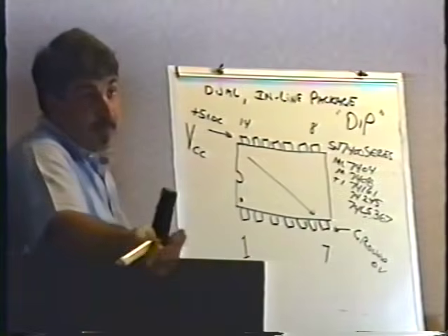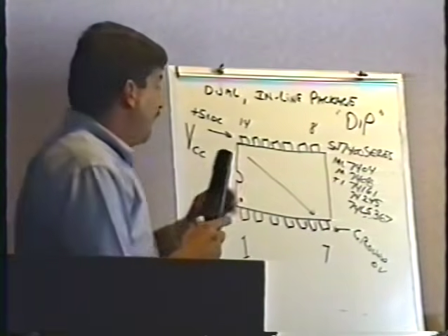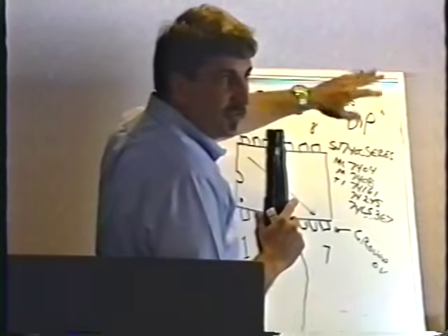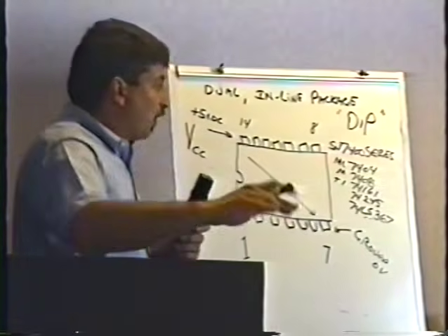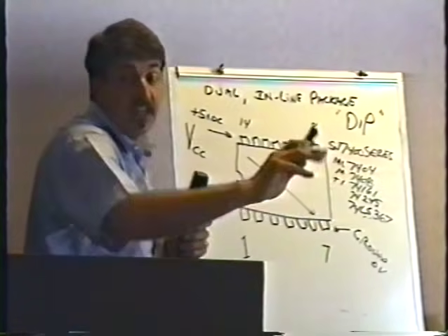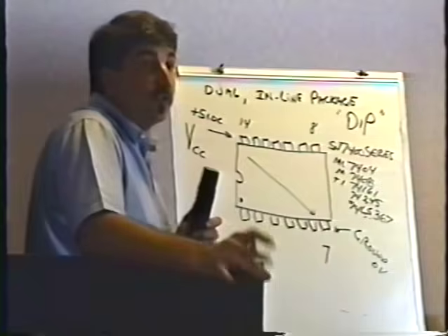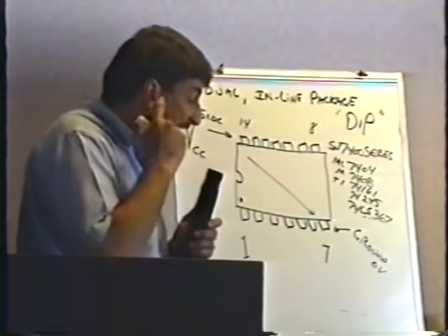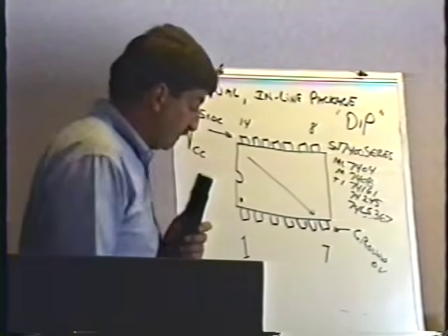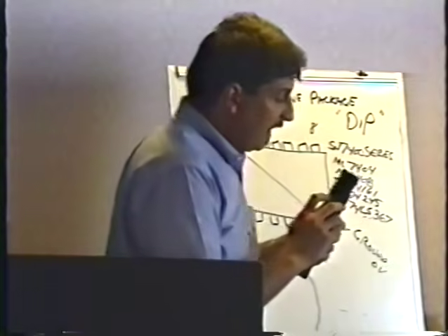That will change depending on who makes the chip, whether it's made by Texas Instruments or Signetics or Motorola or anybody. What we're looking for is the first 2 numbers. And if it's a 7400 series, those are the ones I'm looking for. And with the power turned on, I just go right across those chips. Now, when you do this, really important, it's very easy to slip with your meter lead. So you want to be careful because the power is turned on now.